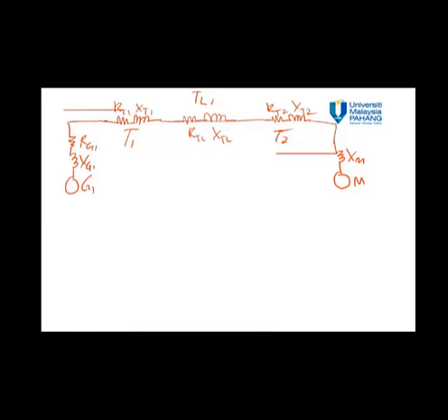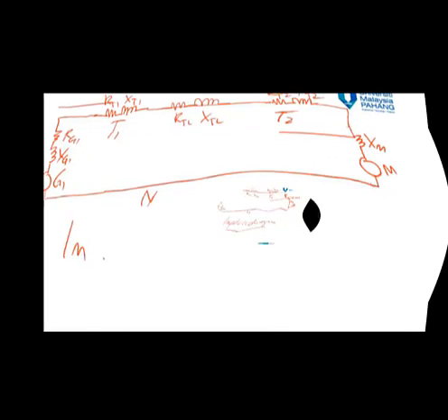But this circuit is not a closed loop, so we cannot do any analysis for an open circuit like this because the current will not flow. That's why we have to add the neutral line to close the loop and complete the circuit. Now the circuit is complete, and then we can start our analysis. This is how we draw the impedance diagram.